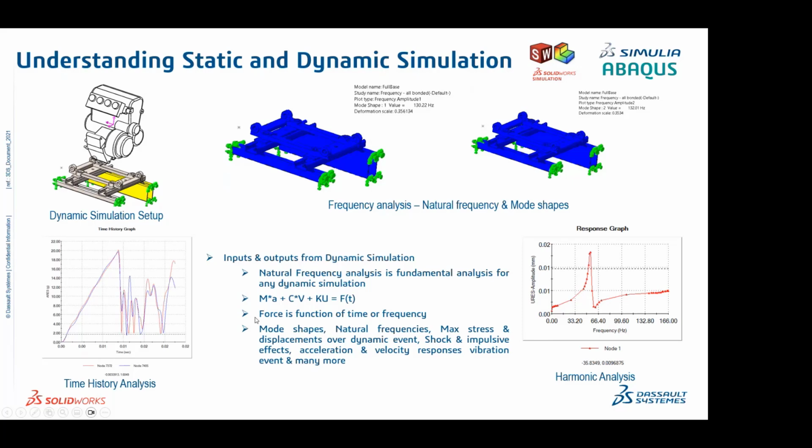With respect to linear static analysis, I told you it is constant and gradually applied. But when it comes to the dynamic behavior, because in the real world nothing is static, everything is going to operate. So this applied load might vary with respect to time. For example, in a shock or impulsive or impact kind of test, the load magnitude is going to change with respect to time. That is where the time history analysis comes in. Or the load might be with respect to frequency, where random vibration or harmonic analysis comes into the picture. I will explain in detail in the coming slides.